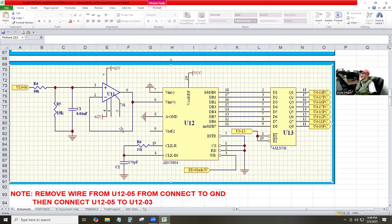If it's not, that means the connection from here to U10 has a problem. If it is, that means resistors R4, R5 have a problem. They must be 5K each, and that's just a voltage divider. Okay? Divide by 2.